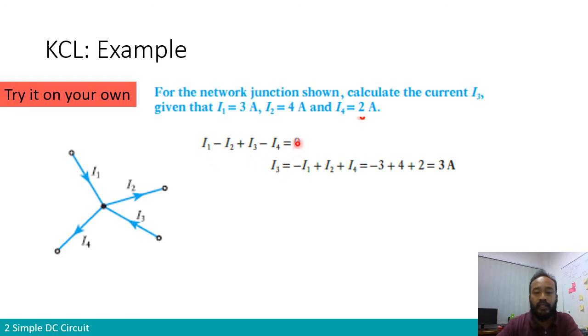The most important thing in KCL, if you want to find parameters using KCL, is to write this KCL equation. As you can see, the KCL equation says the sum of currents going through a node equals 0. So it needs to be an equation of current, and it is on a particular node. If you have an exercise, you have to identify the node first, then assign the direction of current, and then write your KCL. It's direct and simple.